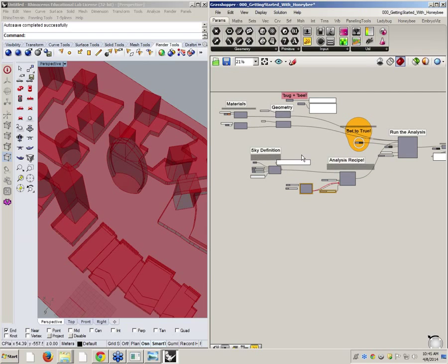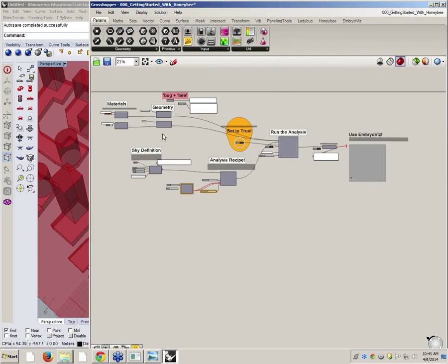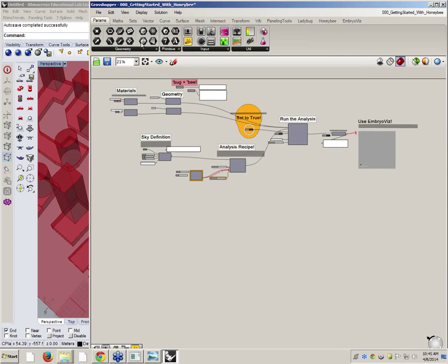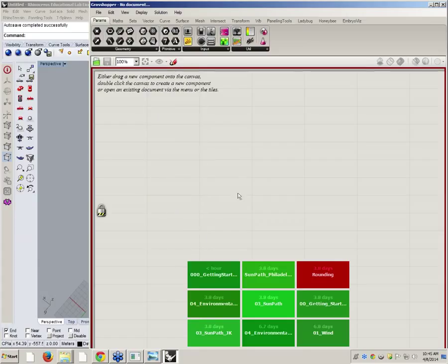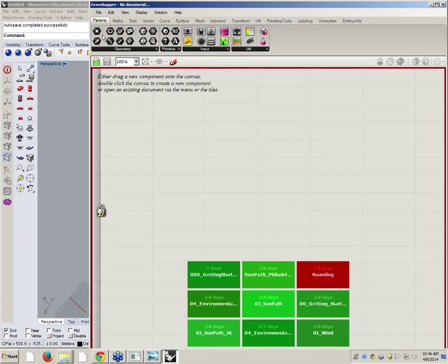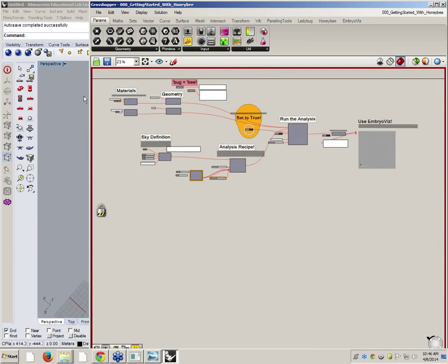Yeah, and if you're sending files to other people, set these things to false. So when you open the file, boom, boom, boom, everything comes up. But just for your information, because I get files from people and you have no idea if they set it to false or not, this is something in Grasshopper you can do. Before opening the file, right-click here and lock the solver. When you lock the solver, it means it won't run. It's also useful if you're changing multiple things and you don't want the definition to be re-executed each time. You just set this thing to lock. Now I go ahead and open this file, and it won't run anything.